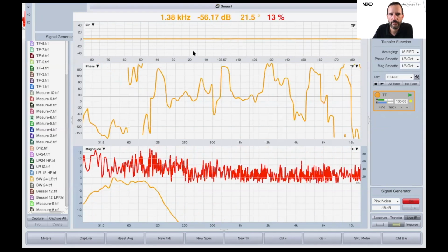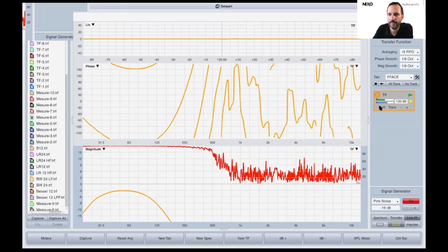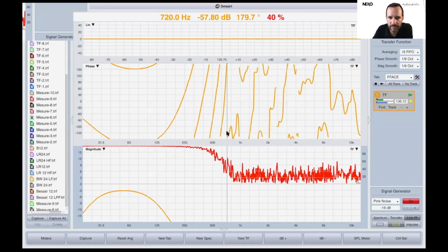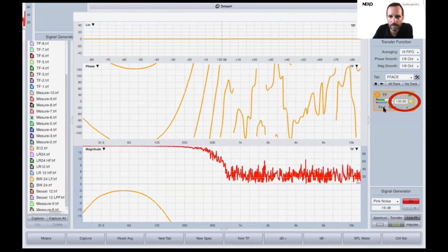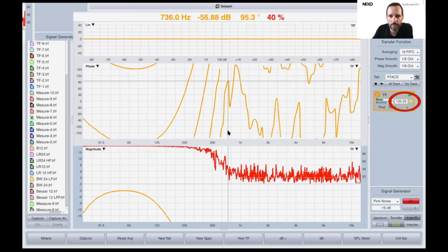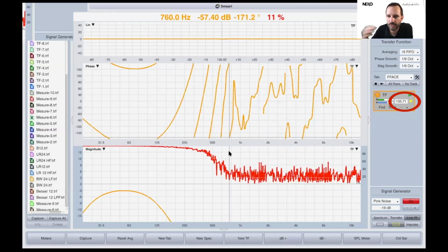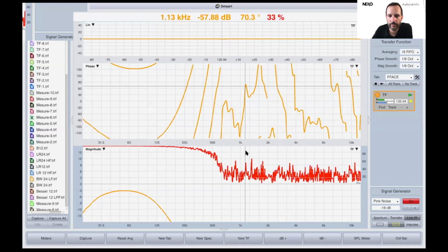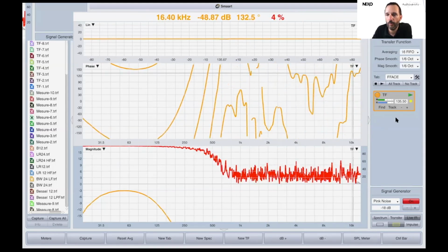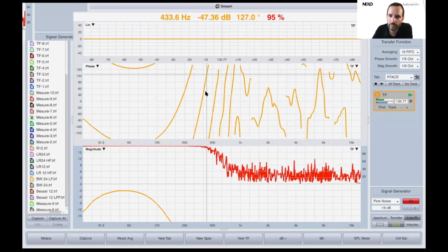So I will cross over at 120. And what you see here is you cannot visualize anything. If you want to find the impulse just by looking, it's like, well, this is 135. If you find it again, now it goes 35, 38. So it doesn't really know. It's still changing, and the reason is that we don't have any impulse. We have nothing. So in that case, the only thing that we can do is just to have a look at the phase trace.